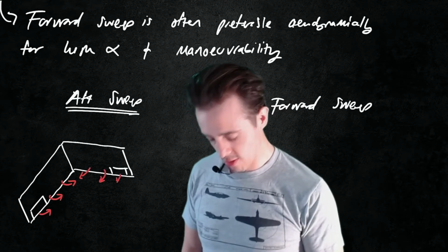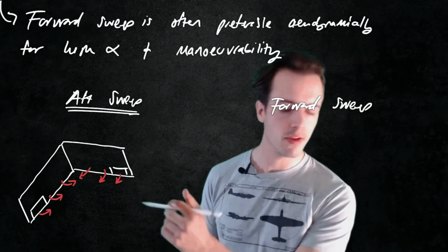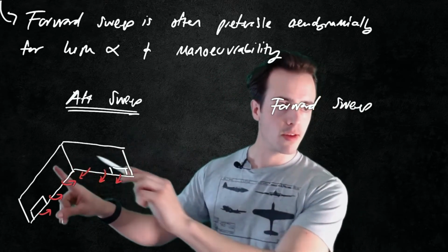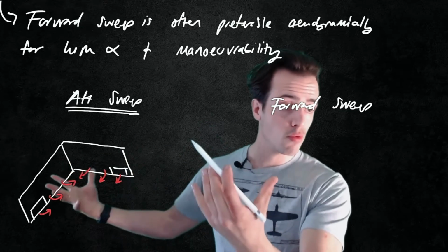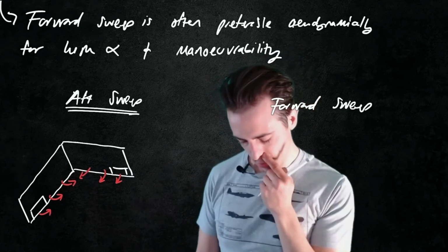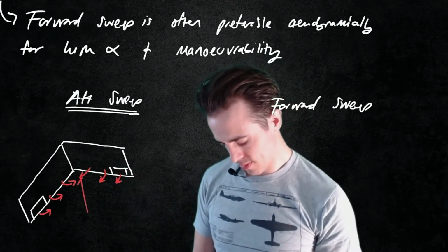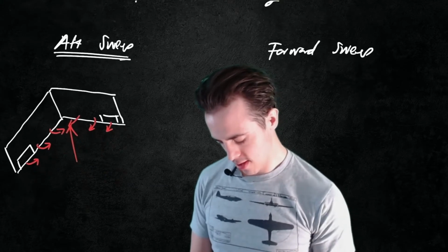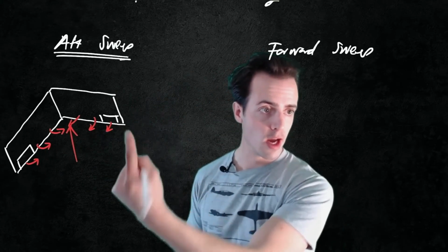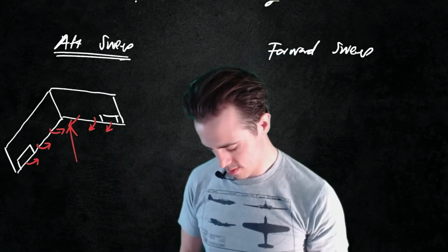You can probably remember this from 312 aerodynamics of aerospace vehicles. In the circulatory theory of lift, the pressure difference is sustained by a bound vortex, and if we increase the strength of that vortex, we've got to shed an equal and opposite amount into the wake. Now, when we've got aft sweep, these root sections cause this circulation to be shed into the wake, which causes an upwash at sections outboard of there.